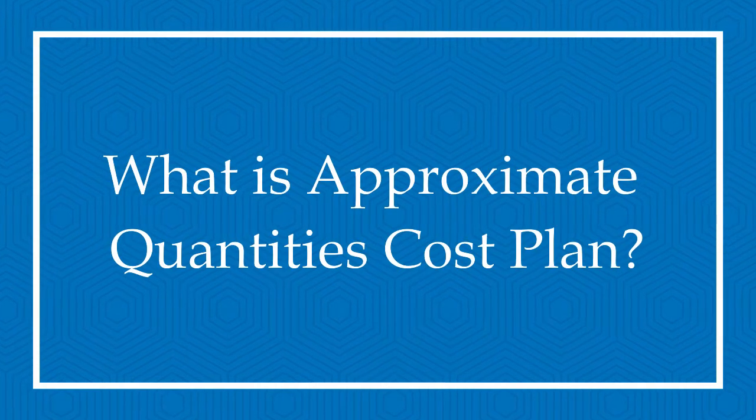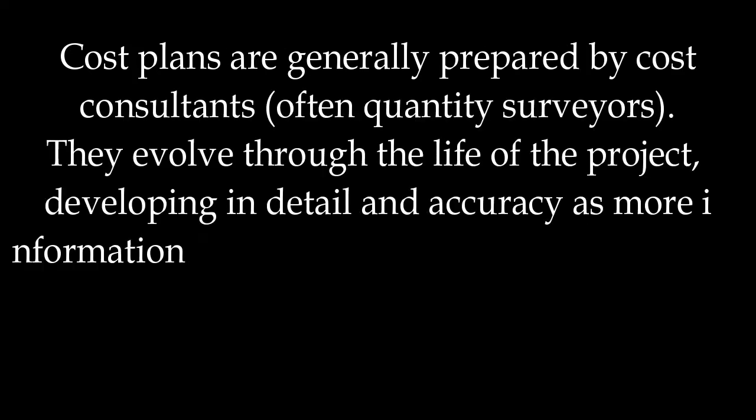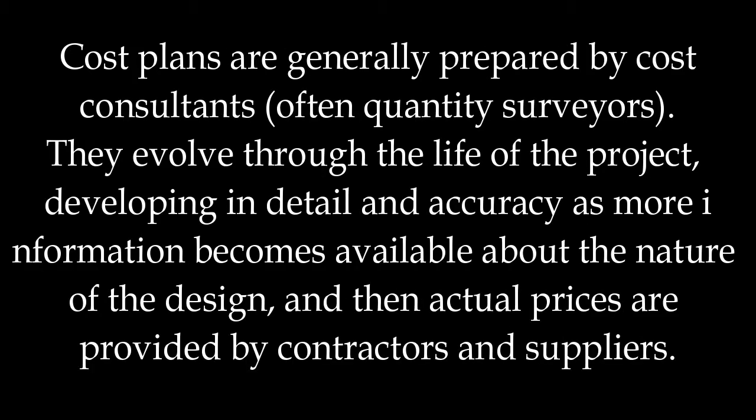What is an Approximate Quantities Cost Plan? Cost plans are generally prepared by cost consultants, often quantity surveyors. They evolve through the life of the project, developing in detail and accuracy as more information becomes available about the nature of the design, and then actual prices are provided by contractors and suppliers.